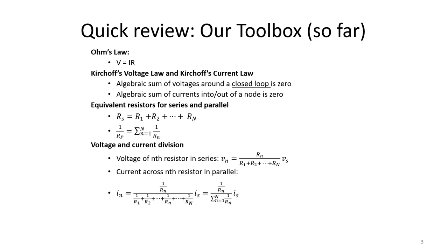Notice we have our Ohm's law, V equals IR. We've got Kirchhoff's voltage law, Kirchhoff's current law. We also have equations to simplify resistors in series and parallel. And we have those equations for voltage and current division.